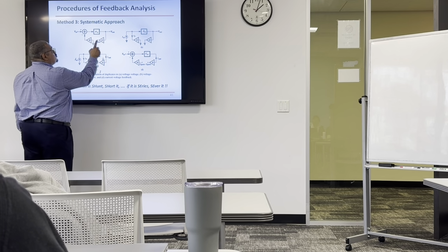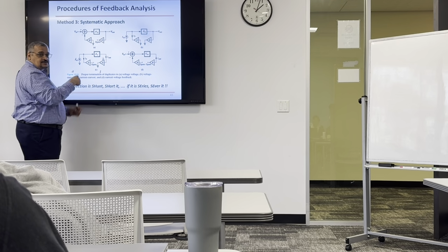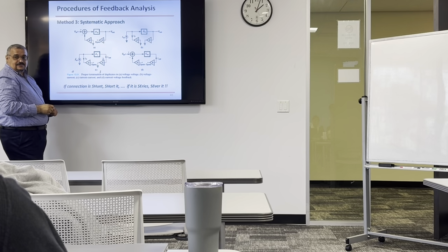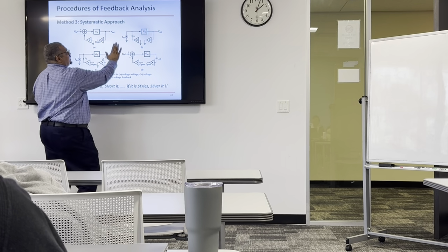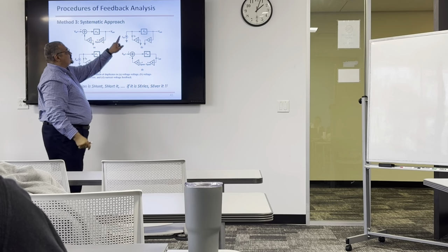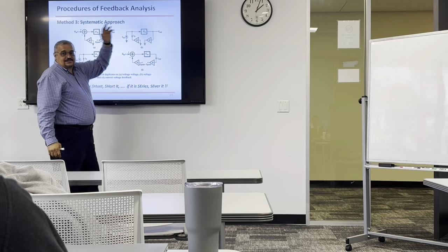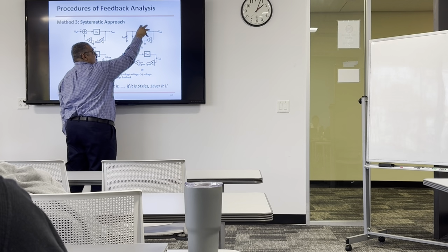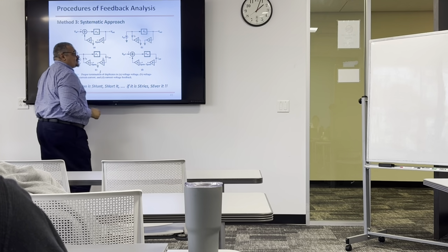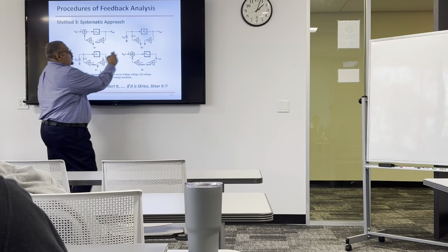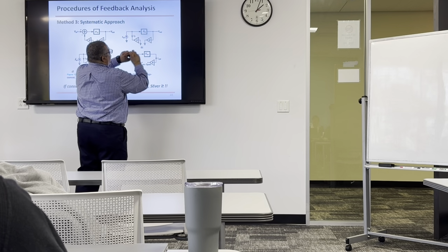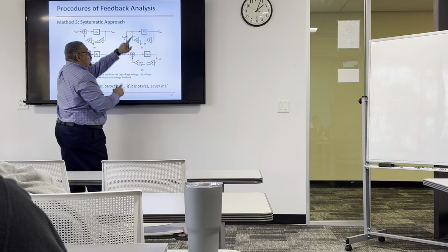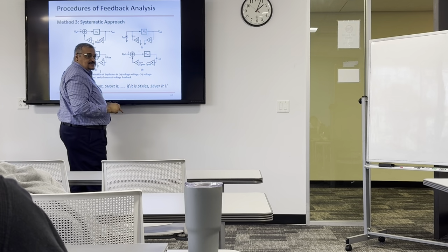Okay? How do you mix a voltage? How was the voltage mixed? Series. Leave it alone, leave it open. Okay? Same thing here. This is a current to voltage. What's the meaning of this? Current to voltage is a transresistance amplifier. So the main amplifier is going to be transresistance. The feedback network is going to be transconductance. You remove the transconductance feedback network and you repeat it twice, one connected to the output, one connected to the input. What to do with the other two terminals?